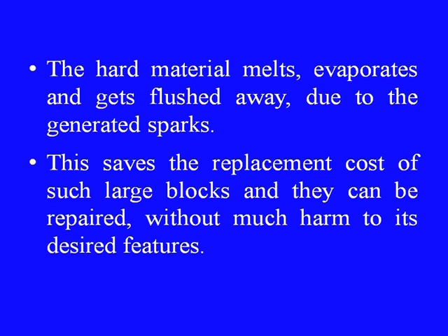As EDM is a localized machining process, it can be readily used for removing the broken taps and drills or tools from the passage. In order to achieve this task, a suitable tool a little smaller in diameter than the embedded tool is prepared and the block is machined by EDM in this localized area. The hard material melts, evaporates and gets flushed away due to the generated sparks. This saves the replacement cost of such large blocks and they can be repaired without much harm to the desired features.